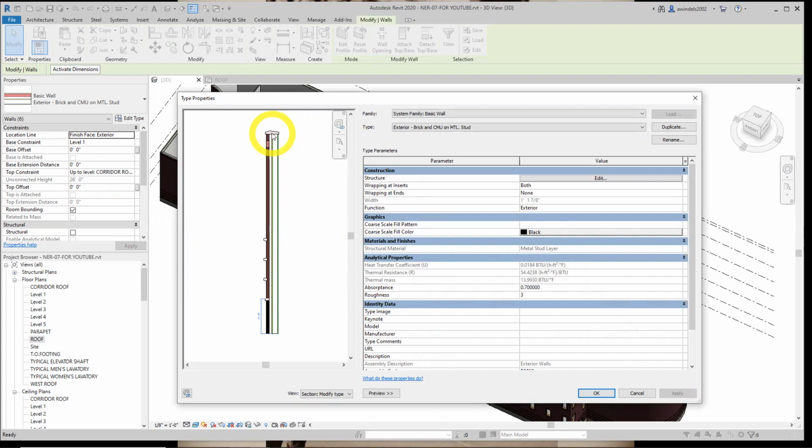So we'll start by using this exterior wall. It's everything we need, but minus one thing. So why not use this one as our example to build off of? That's kind of the idea of this. We're going to call it the same thing, just no parapet on top. Say okay. And we're going to go similar to what we've done a few times.